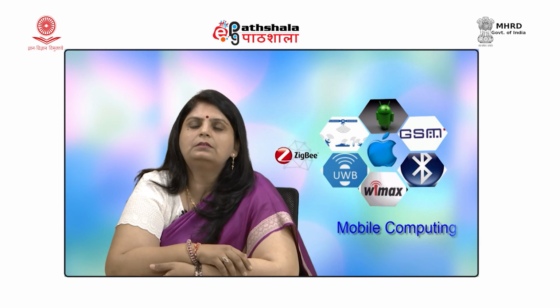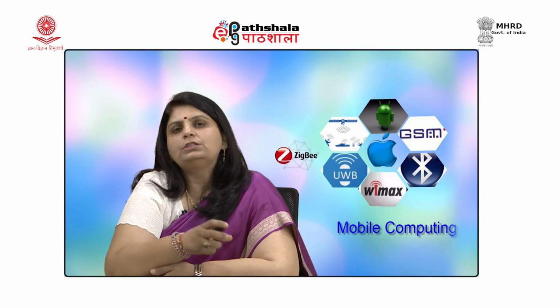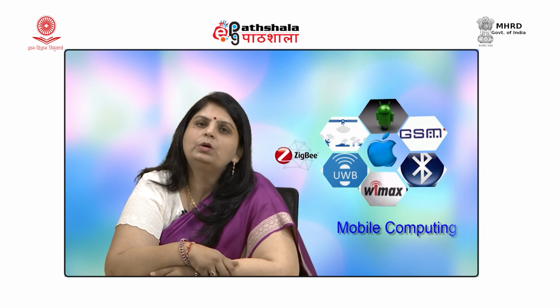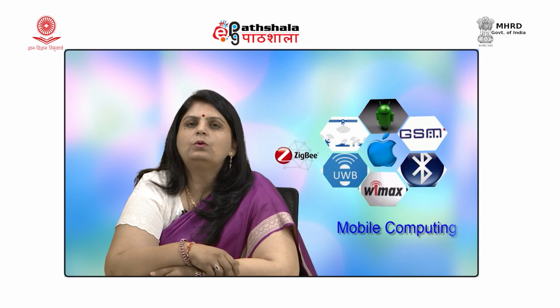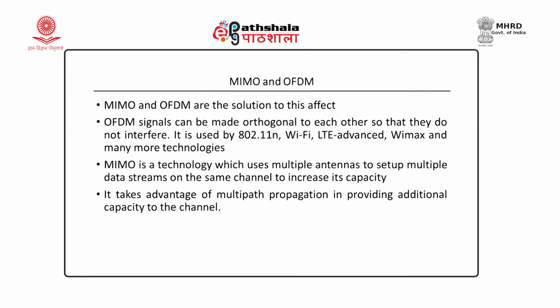Now, that adoption is the introduction of 2 technologies, MIMO and OFDM. MIMO stands for multiple input, multiple output, and OFDM stands for orthogonal frequency division multiplexing. In orthogonal frequency division multiplexing, the signals are orthogonal to each other, so they will not interfere at all. So, no constructive or destructive interference. This technology is used in 802.11n, Wi-Fi, LTE Advanced, WiMAX and many more technologies.